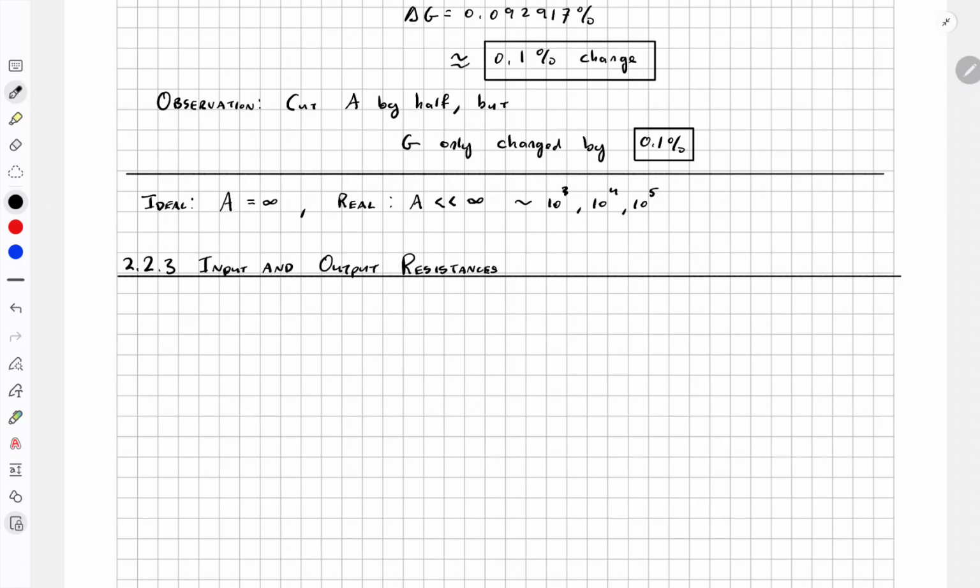So let's reintroduce the same circuit for the inverting configuration that we have been working with so far. Just to review, it looks like this. You put the input here, put R1 here, then you have your op-amp triangle here. You ground the non-inverting terminal. You pull your output and you need a feedback. So this is the inverting configuration.